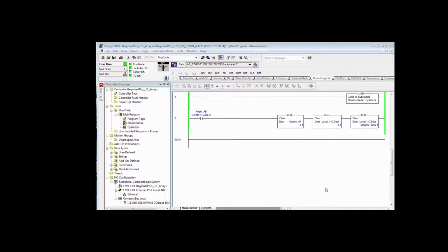Somewhere along the way, we added a reset rung to reset these bits to make it easier to do repeated exercising of your logic, rather than going back, right click, toggle bit to clear everything that you latch. Now you'll realize here eventually, if you haven't now, that latching logic isn't the best way to go, because when you latch bits or you use latches, then you have to, as we say, unlatch the whole world.